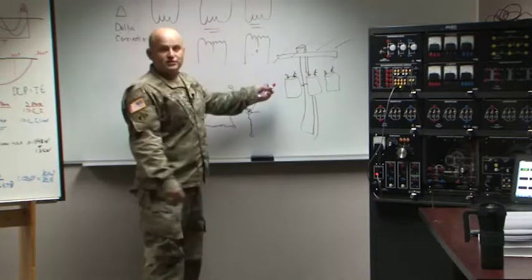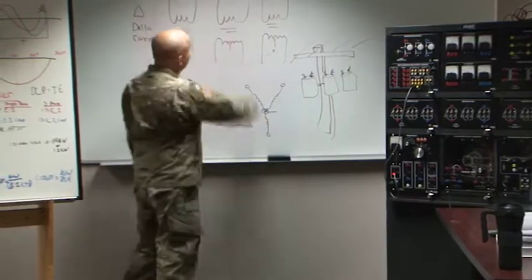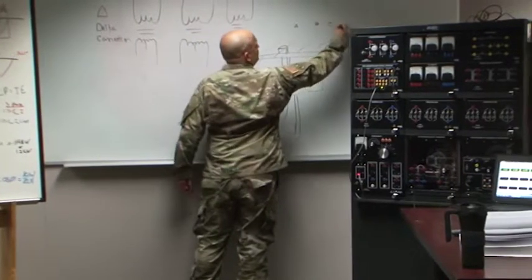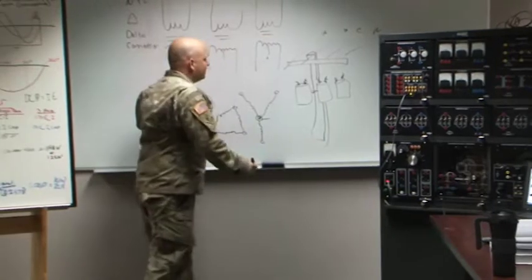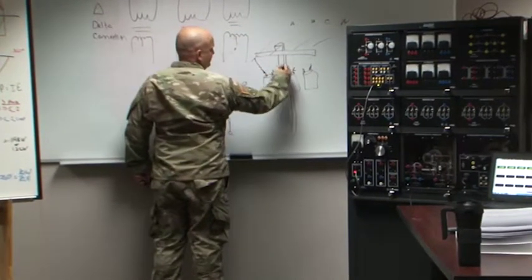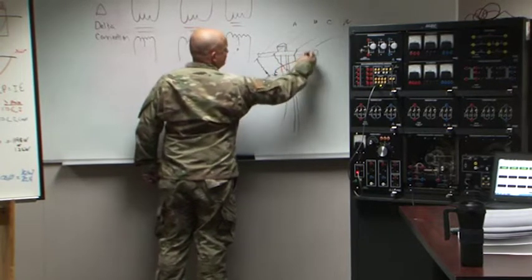Well, right now, because I just drew H1 and H2, I'm just talking about this part, the primary connection. So all that I drew here would be the same if this is A, B, C, and N. Would be the same as me going, okay, well, I got my jumper to A. Got my jumper to B. Got my jumper to C. And then these jumpers are going over here to neutral.